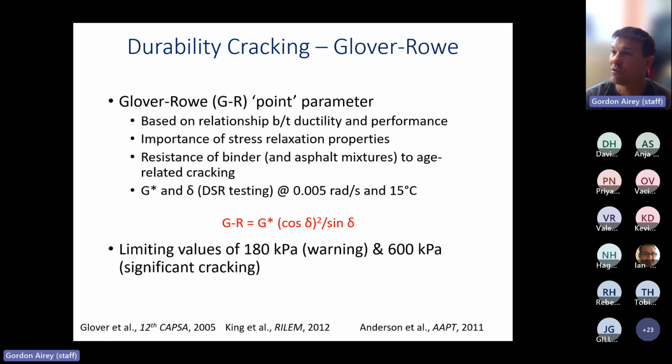I said I'll talk about Glover-Rowe and durability cracking. Just a little bit of background. The Glover-Rowe parameter is based on initial work that was done by Charles Glover on ductility and how ductility can link to cracking performance. It's basically taking those same concepts, except we are changing some of the parameters. We're using complex modulus and phase angle at a different frequency and temperature. But again, it's the overall concept.